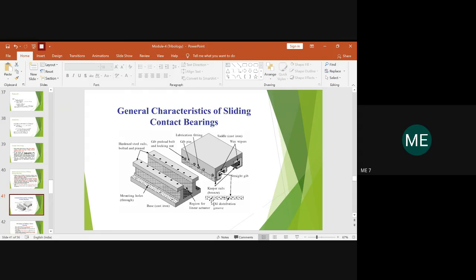So you have an oil distribution in this section, because this is the most important part where the friction comes into picture while moving. In this layer you will have distribution of the oil, so when it slides to and fro, the friction will be very less.